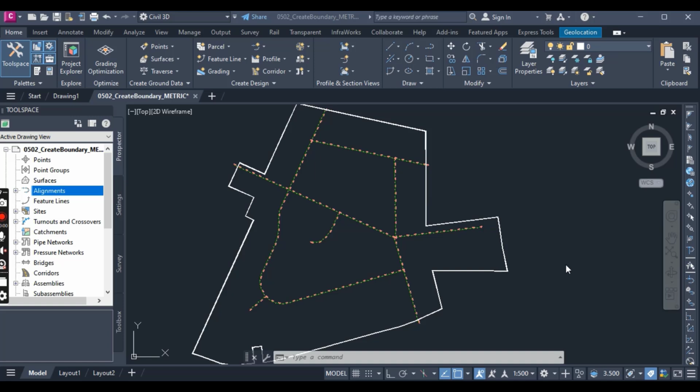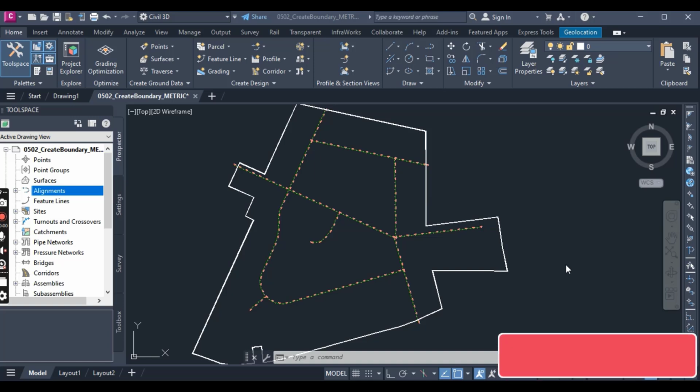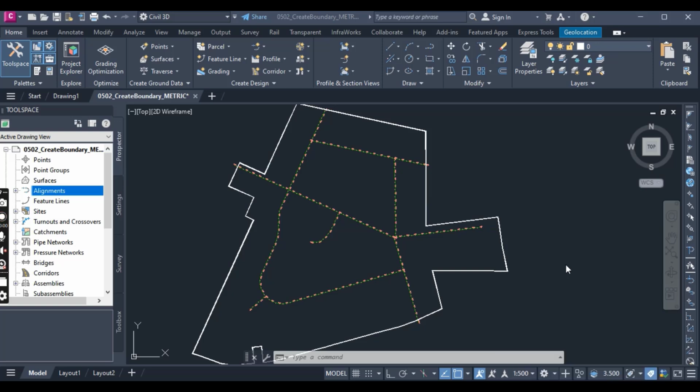Civil 3D may allow you to pick objects with an elevation other than 0, but you will get better results if you flatten the objects so all objects have an elevation of 0. Sometimes the geometry appears sound when elevation is applied, but you may notice that this is not the case once the objects are flattened. Flattening all objects before creating parcels can help you prevent frustration when creating parcels.